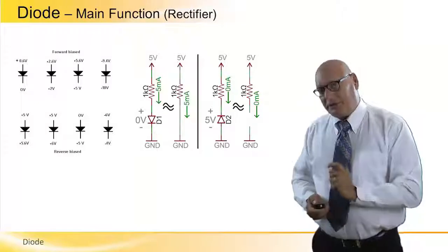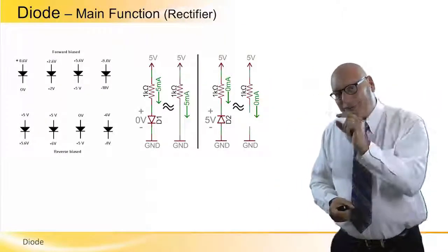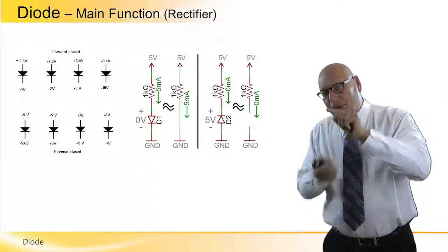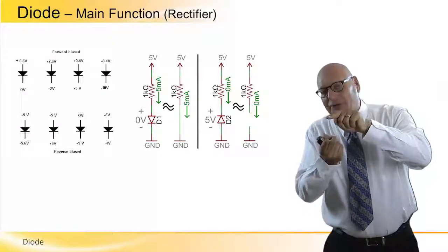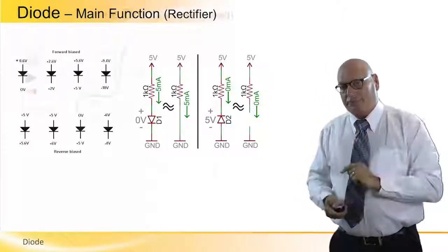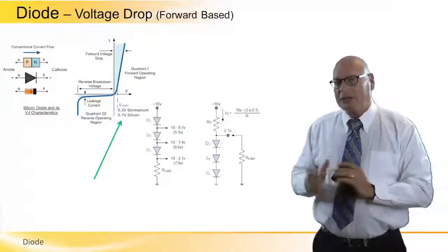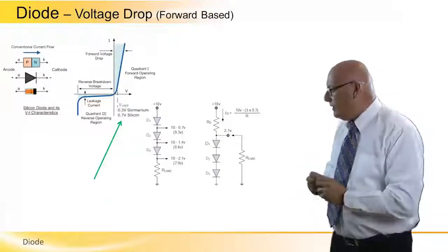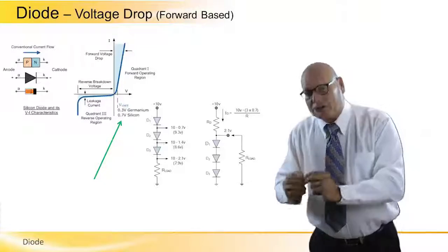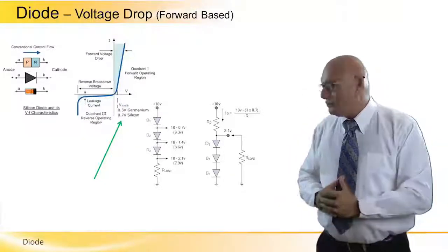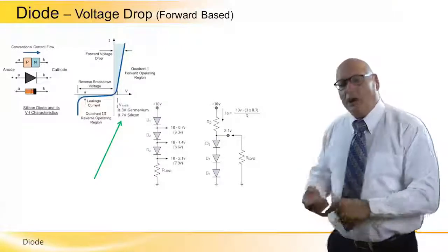Later on in the seminar, we'll talk about the difference in the potentials between anode and cathode. What should be the minimal difference in order for these diodes to conduct or not to conduct? And we just got to this point, and I want to mention very specifically that there are two technologies of making diodes, as with making any kind of semiconductors: germanium and silicon.